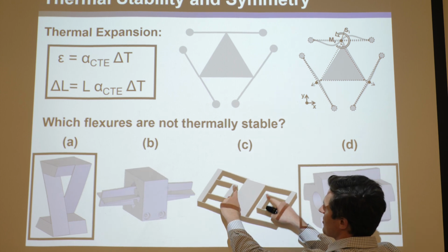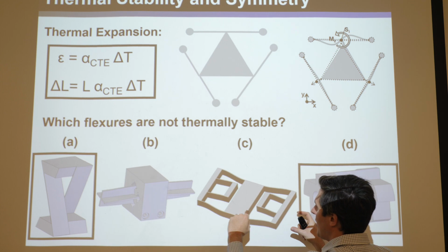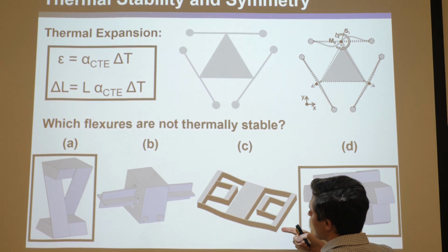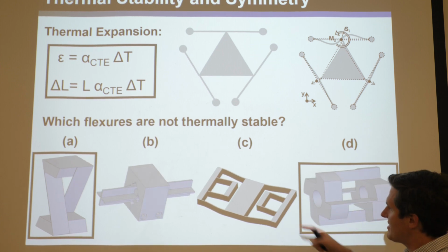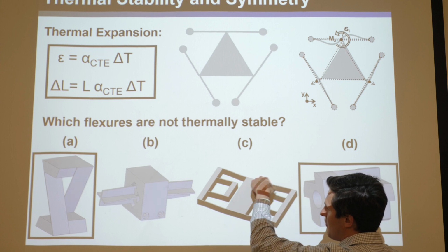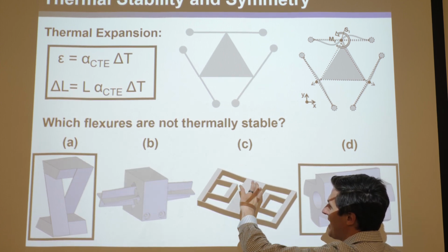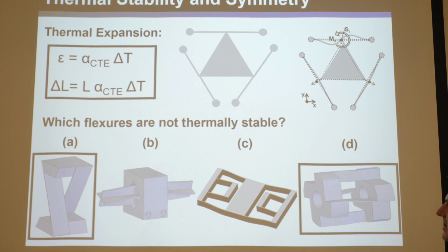So these guys are grounded. These are intermediate bodies, and that's the stage. If you heat this up, these guys will grow, but these guys will also grow. And so these guys will accommodate these so they don't even have to buckle. So this stage, it's moving because I'm showing it actuating, but if you just left it be, this stage would largely not move at all, and there would be no frustration from buckling.